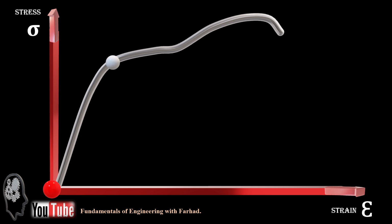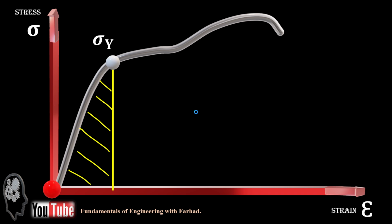The first part of a stress and strain diagram, up to sigma y or yield stress, the area under this part is called modulus of resilience, and most of it is in the proportional limit.